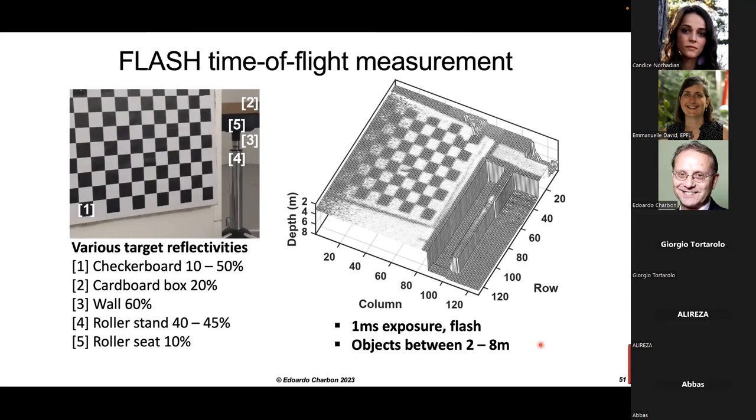Okay. No, I did not mention PVT. I mentioned the sensitivity of DCR to temperature. And the rule of thumb is every 10 degrees, you double the DCR, dark count rate. So you definitely have to be aware of the temperature. And that is very important in space because there may be some large variations of temperature which need to be taken into account. Nevertheless, this can be done automatically. And since the characterization can be done a priori, it should be possible to compensate for that.